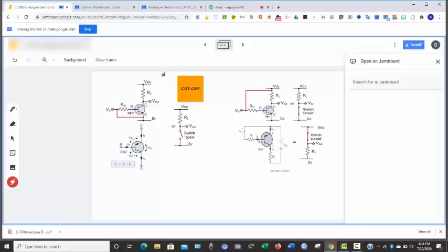And with that, you can design this transistor to work as a switch. If you look at what we have in this case, this is a switch. This is more or less like an ordinary switch, and this transistor will mimic that. So in the cutoff region, it appears as if there is no flow of current. It appears as if the switch is open.